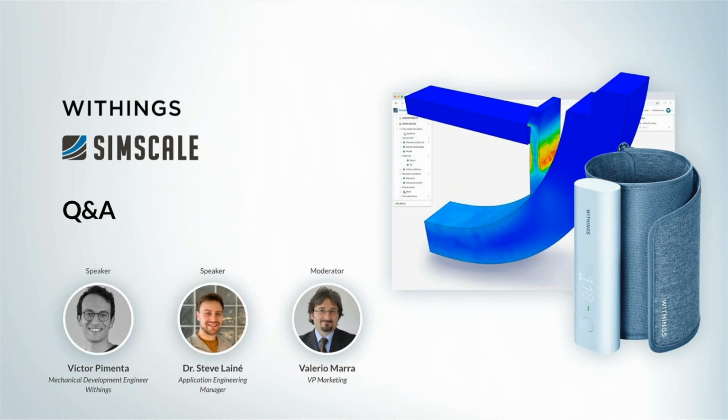So we defined it as the focal point of our simulation. Therefore, all the nodes from the plastic casing were constrained to the master surface, the master entity, which was the PCB. And to match it all, we had to define which points are more fragile and which points are sharper than the others.